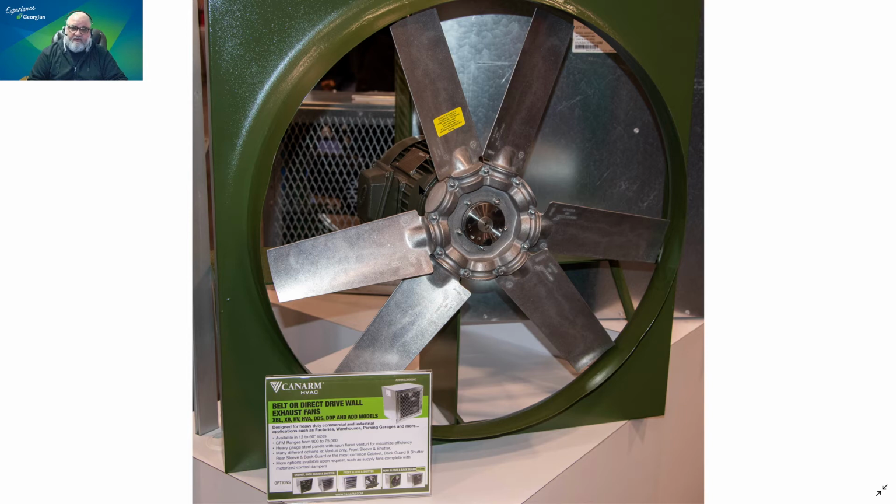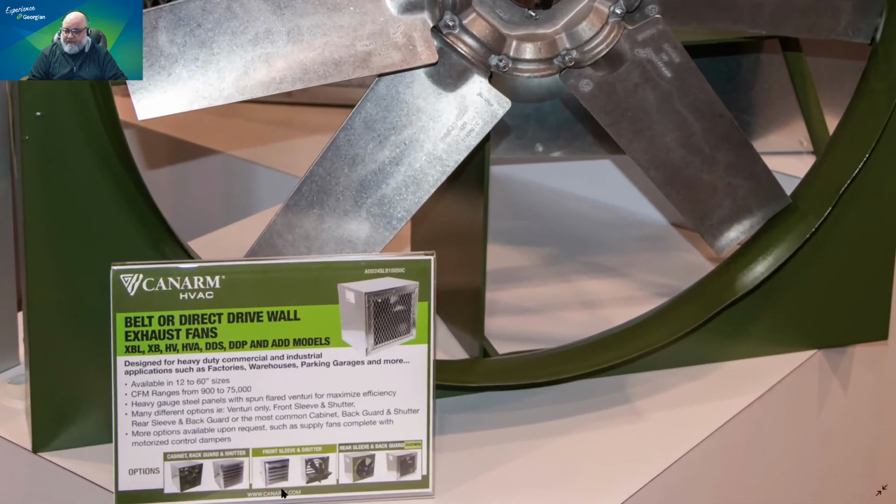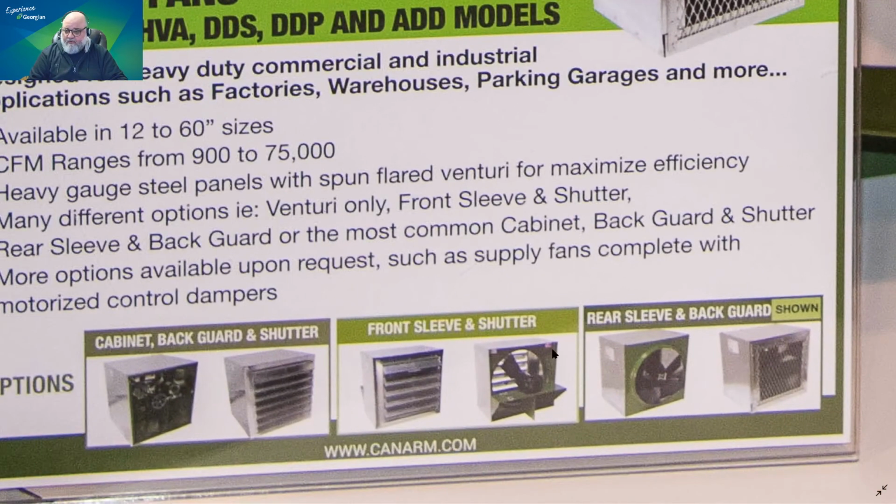You replace the motor and it's burnt out again in a couple of days because you didn't fix the problem. You just replaced the motor. So one more time, different types of blades have different types of characteristics. This guy here, this is the propeller. They hate resistance to flow. Therefore, in all applications, like if you see the applications, they are all boxed.